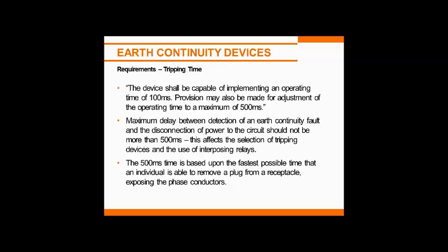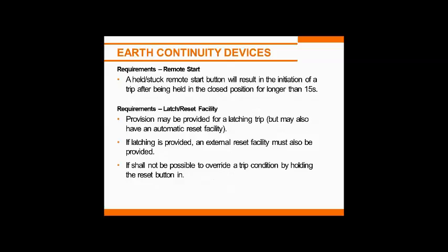Most of our systems in the field are probably set to about 150 milliseconds. Usually the quicker the setting, the safer the relay or the system is.